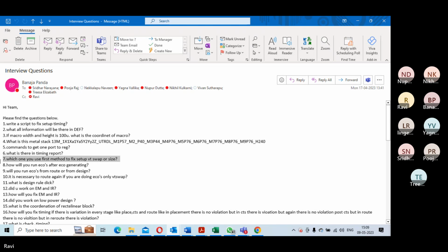Now you will do the hand placement or place the cells close by. Even in the ECO, place this cell over here. It should be implemented such that the cell does not have any free movement wherever it wants. The ECO should place the cell appropriately where it is connected.